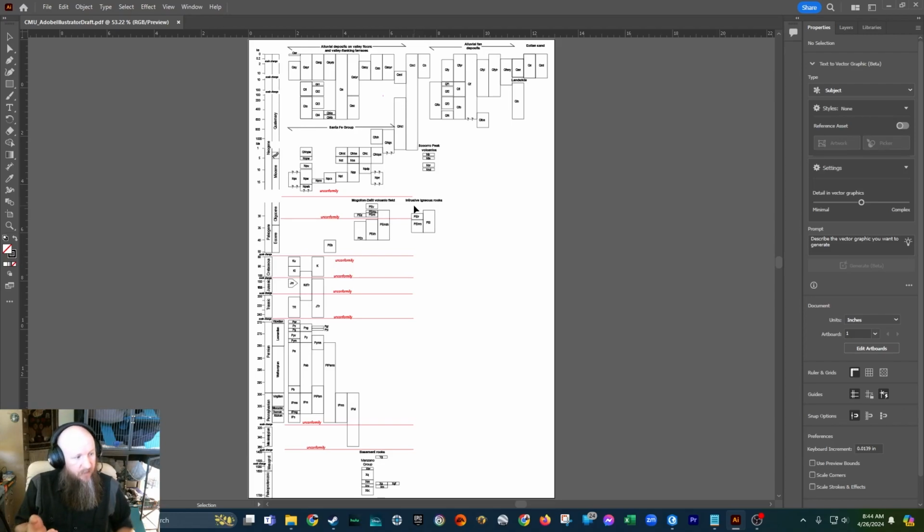And one of the other comments I'm going to make is this is at a 1 to 100,000 scale map. So we're going to start with that as kind of a foundational discussion point because it relates to the size of the boxes. And that's one of the things that we want to establish and make sure that we're always doing in our correlation of map units. The box width, the X direction of our map unit boxes, our polygons, should be 1/2 inch wide so that they're always universally the same size, the same width across the correlation of map units.